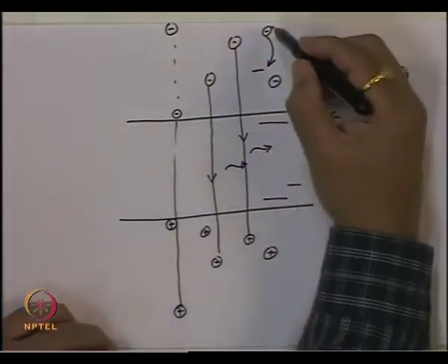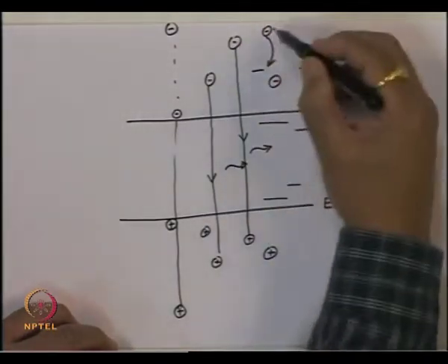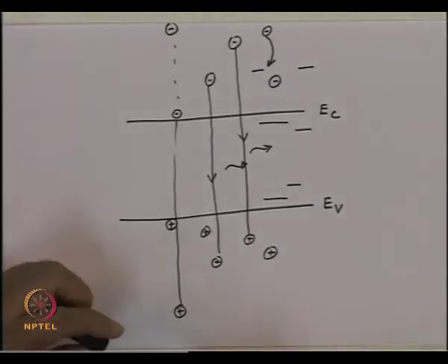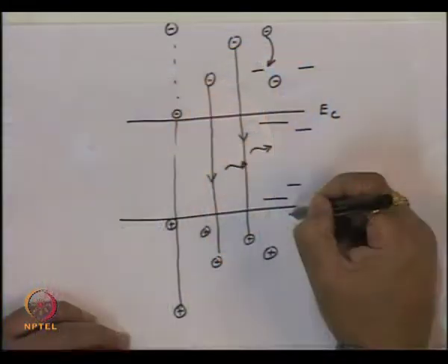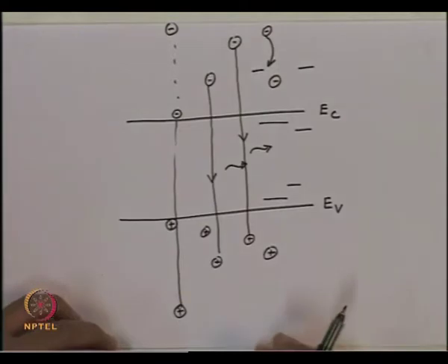Or in other words, the electron hole pairs which have a very large energy difference, they will be depleted. So, you will have less photons corresponding to the very high photon energies, and you will have a little higher number of photons for the energies which are less than band gap energy.